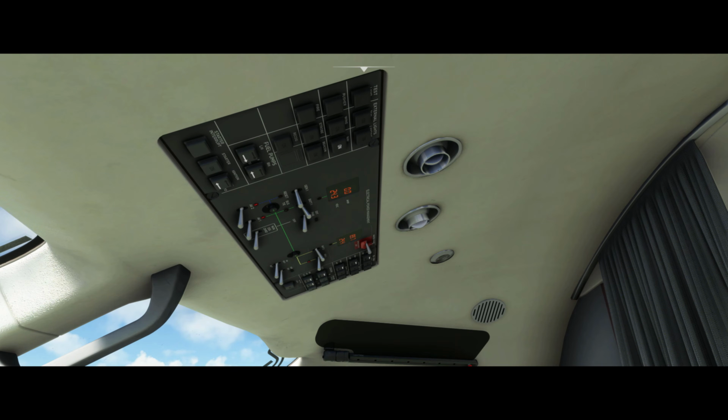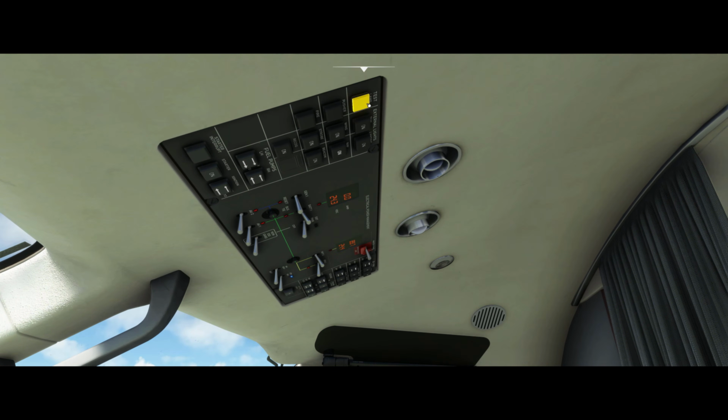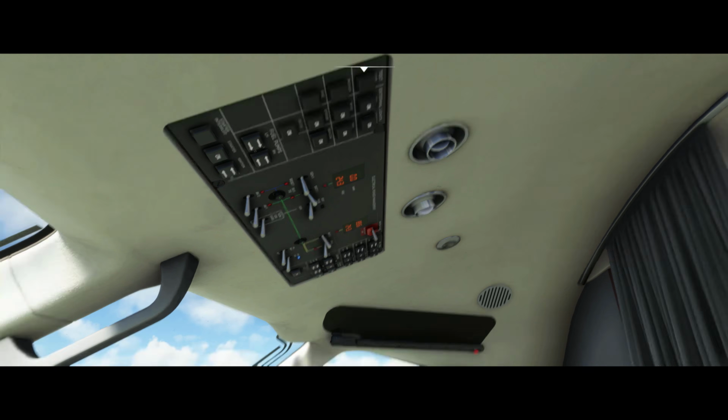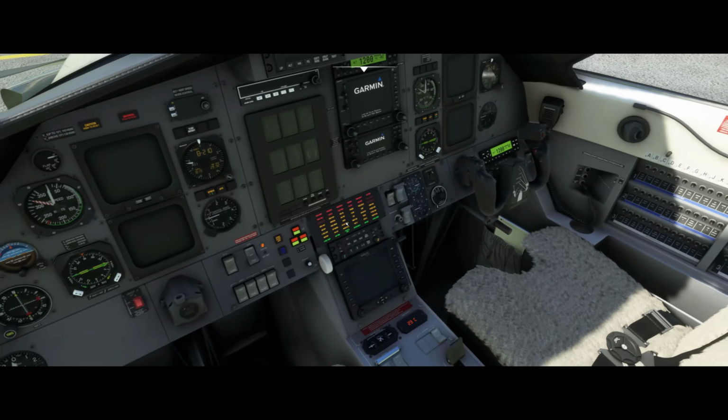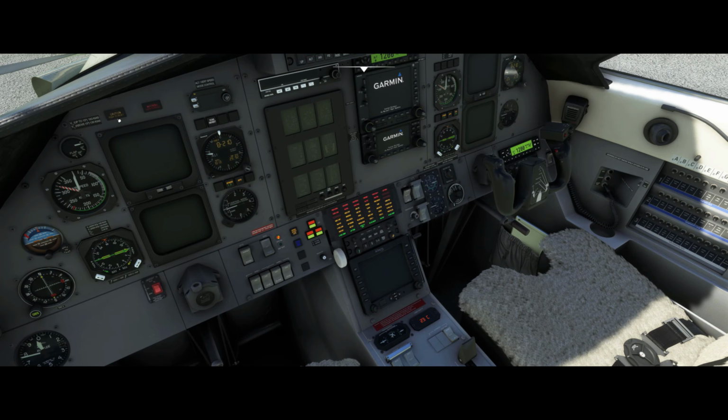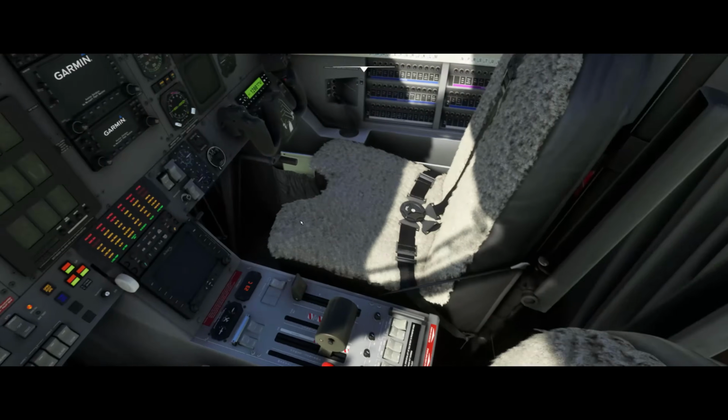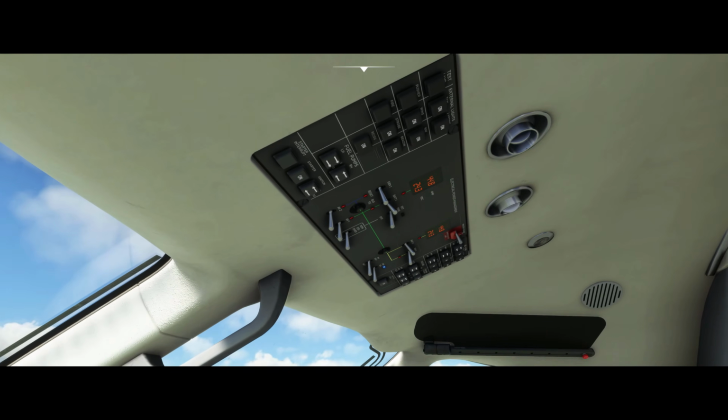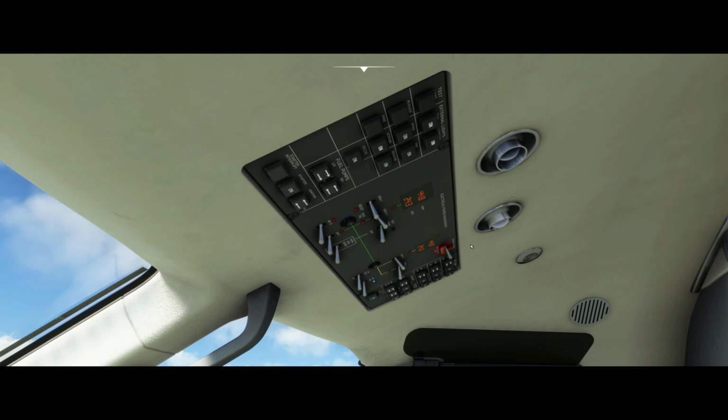And then at this point, I would perform a lamp test. So if I push and hold that button, all of the lights that can light up, light up. And I'm just checking to make sure nothing's burned out on the CAS or any of these other lights. So those look good. And in the sim, I think this will just sort of time out after 5 or 10 seconds. There it goes.